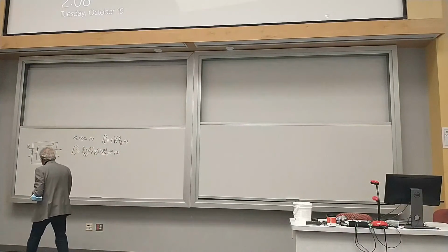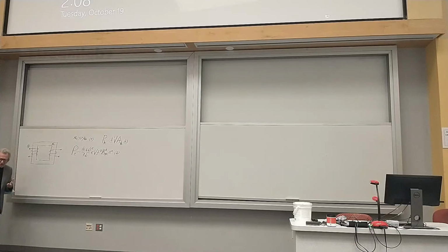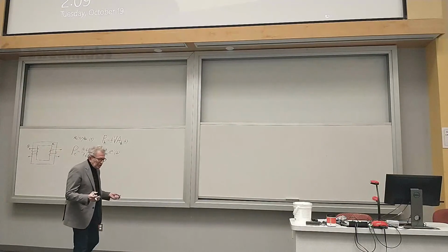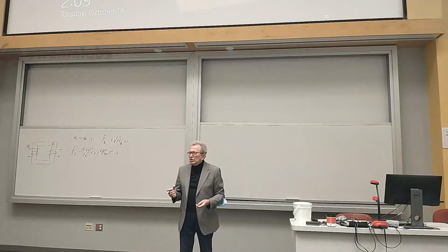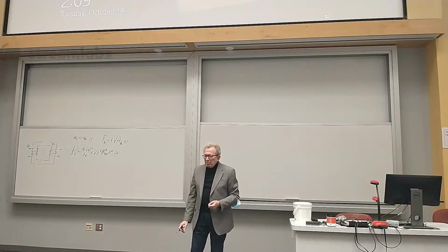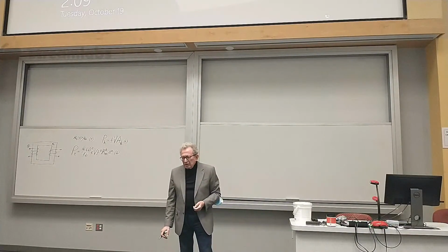Then we started the discussion of the transformer, its design. The transformer is a static device in which two or more coils, which are called winding, are strongly electromagnetically coupled. This strong electromagnetic coupling is achieved because you put the winding on the same ferromagnetic core, wound them around the same ferromagnetic core, and use high magnetic permeability. So the ferromagnetic core, of course, is laminated. It is transformer steel. Transformer steel means that it's doped with silicon. It's laminated.